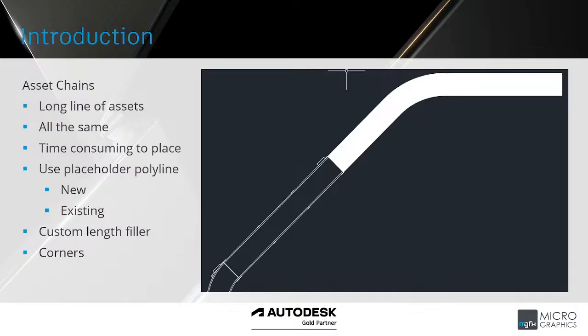So this automates the process of placing down assets. As an example here, on the right-hand side, we've got a polyline coming off the conveyor belt, representing maybe new conveyor belt that's going to be added to expand the production line. And the polyline has a width. Now, I've drawn this with a radius in the corner. You actually don't have to. You could leave the corner sharp, and the asset chain will replace that sharp corner with a corner asset with the default radius that is used. In this case, I've drawn it so I can get a feel for what that space requirement is for the radius there. You might not get this with a sharp corner.